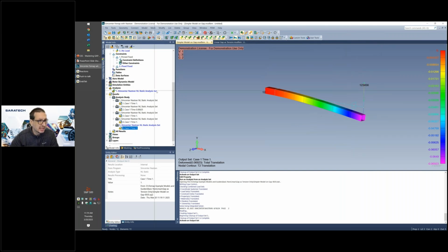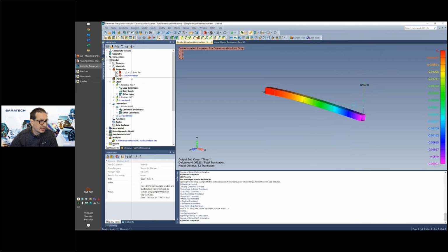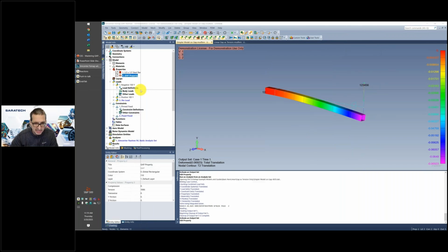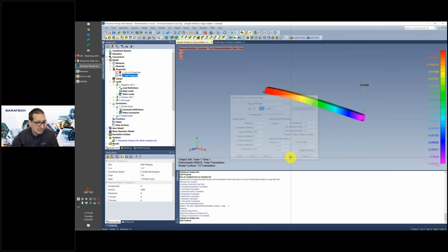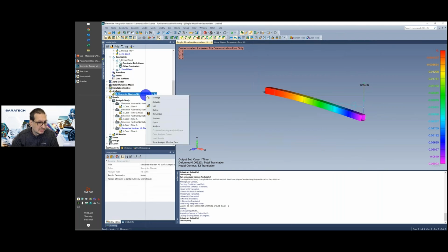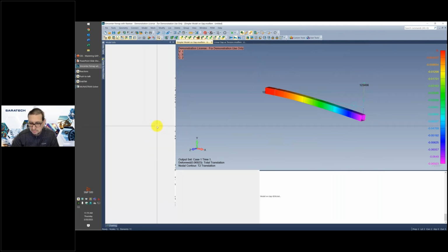So you may think, oh, okay, so that works in the positive X direction of our element. What if we change this to a negative preload force? Is that how we're going to get our tension in our model? Let's give that a quick run and show.